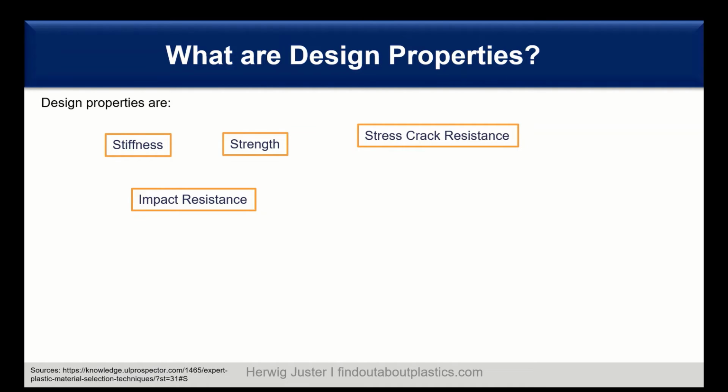Impact resistance, also certain designs allow for a better impact resistance. The same with creep resistance. So you make the wall thickness and the angles of the part in a certain way to keep creeping to a minimum. And also flammability. So with the wall thickness of the part, you can influence the flammability level to reach V0, V1, at different millimeters.